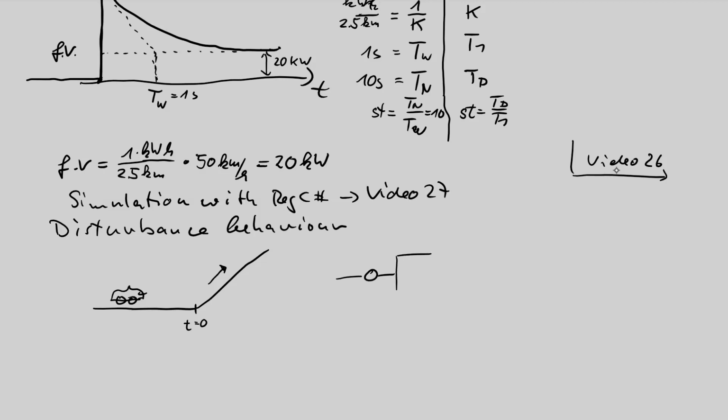I just make a copy of the signal block diagram with one difference. Now I have, as already done in my simulator, a second input with negative feedback. This is my PI controller. This is my PT1 process. And this is now a disturbance, say power index Z, because Z is the typical letter for disturbance values.